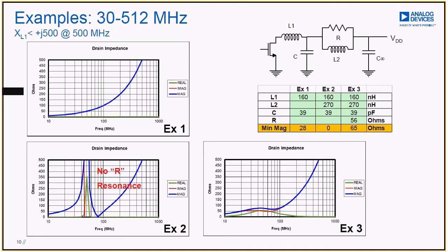Our amplifier is probably going to oscillate at that frequency. We put a very high Q network there, and it's not going to work, and the gain's not going to be flat, and the efficiency is going to change. All kinds of terrible things are going to happen there at about 50, 60 megahertz because we've unintentionally created this resonance in the drain bias network.